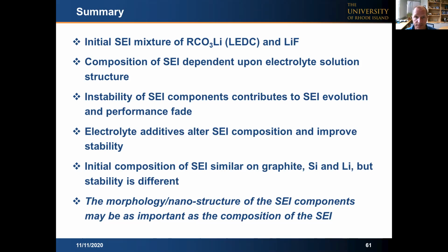In terms of the aging of standard lithium-ion battery electrolytes, the instability of the SEI components, in particular the instability of the lithium ethylene dicarbonate, contributes significantly to SEI evolution and the degradation of the SEI. Electrolyte additives, such as FEC, fluoroethylene carbonate, or vinylene carbonate, alter the SEI composition and improve the overall stability of the SEI.